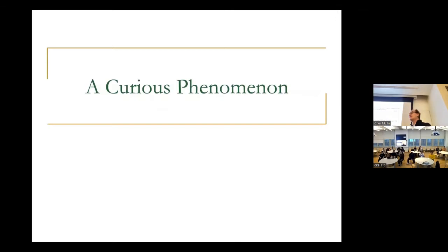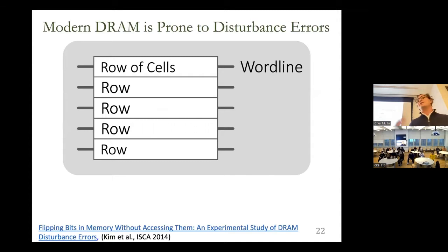Okay, so while we were doing these studies, we actually looked at a lot of different failure mechanisms, and we were also doing studies on flash memory, which I will mention briefly later on. And we saw a lot of disturbance errors in flash memory. And together with Intel, we decided to study DRAM chips in terms of read disturbance. And we found that essentially DRAM chips are vulnerable. So what is this read disturbance phenomenon in DRAM, the RowHammer phenomenon?